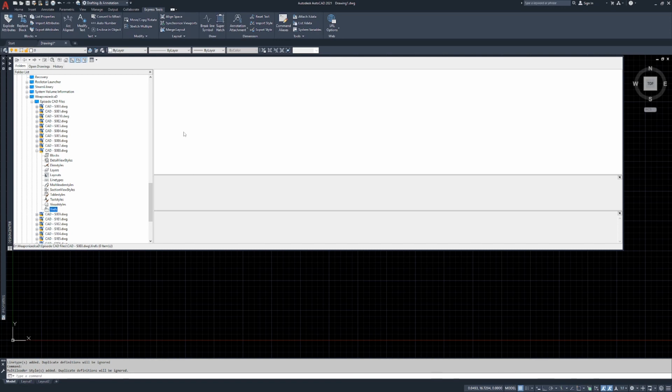So if you don't know where something came from, you're like, oh, I saw a really good text style. I had this awesome dimension style setup, and you're in a position where you don't have a template built, which we haven't done. We have not built a template yet. So we're just adding things to our drawings on the fly. Design Center is how you pull from previously set up drawings into your new drawings, and you rock and roll.